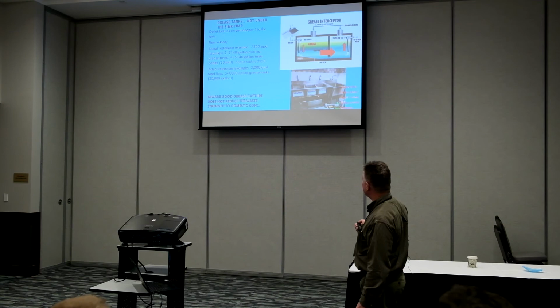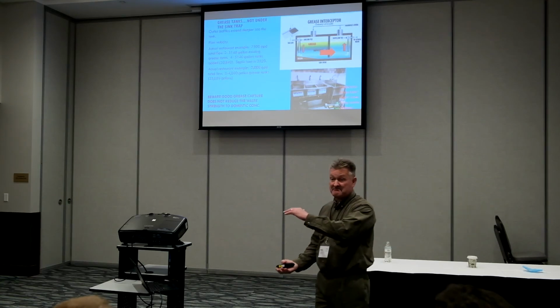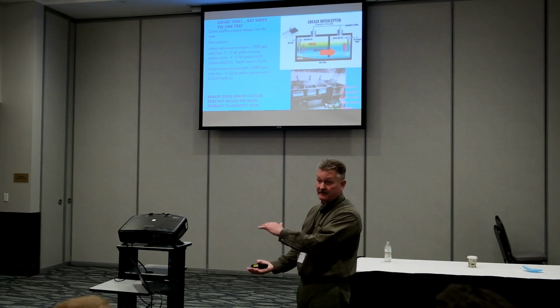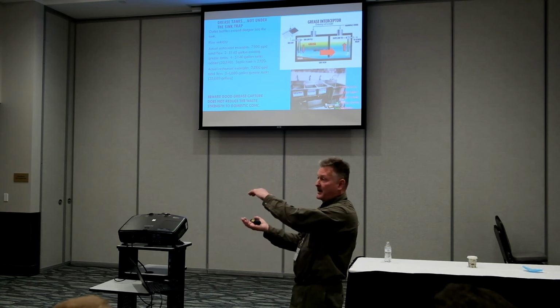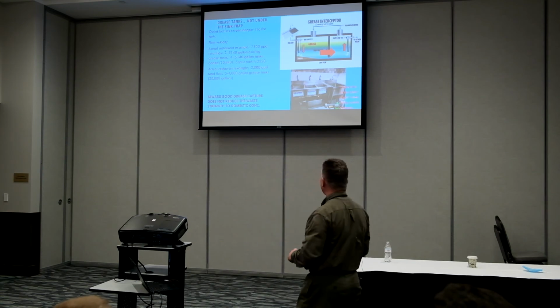So we have a temperature gradient in the tank, warmer water on top, so when the grease and water mixture comes in, the grease has a tendency to rise up and get captured. And then the same thing right here. So a higher grease concentration on top than we would have on the lower part. So that's why the baffles are typically installed maybe 12 to 18 inches off the floor of the tank versus midpoint or 1/3 down like we would on a septic tank.